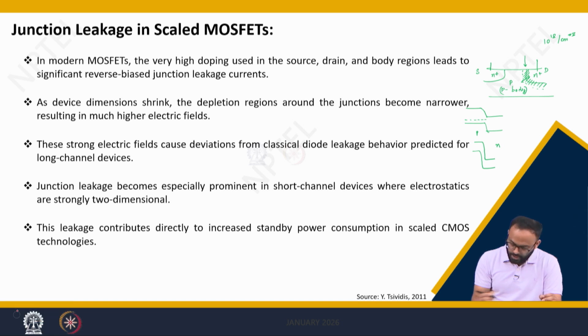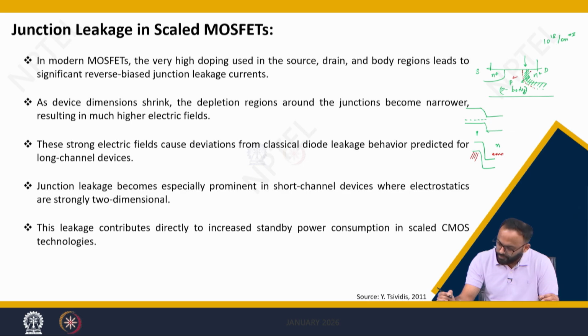Here you have a filled valence band and an empty conduction band. The same scenario is happening here. If the substrate is heavily doped, or even if it is not heavily doped, you have a depletion region here and it can be considered as a one sided PN junction. Because of that, there is a bending. Now, if you increase VDS, meaning you are making it reverse bias, then the bending will look like this.